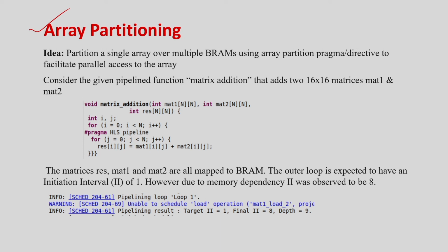pipelining also, right, because if you have more array accesses in the loop and you try to pipeline, you may not achieve a pipeline initiation interval of 1 because of these access limitations. Okay. So, array partitioning is something important, and the high level synthesis tool does support that, right. So, for this I have first taken a matrix addition example, and then I will move on to matrix multiplication and how array partitioning will help there.